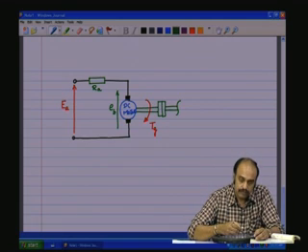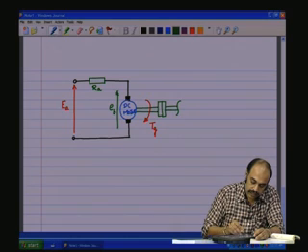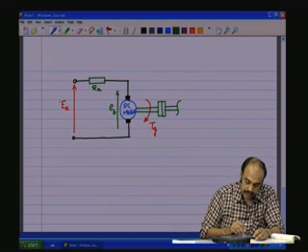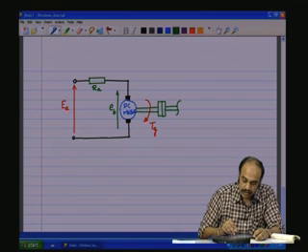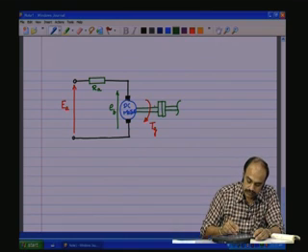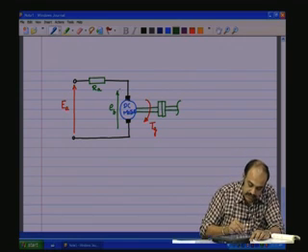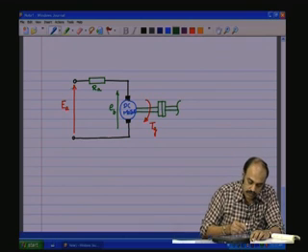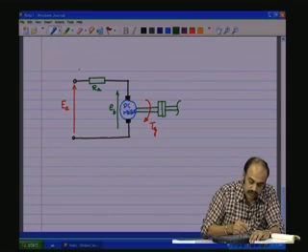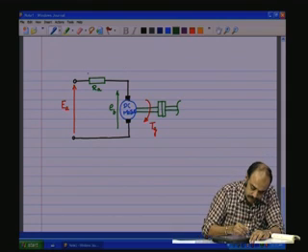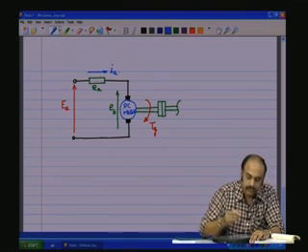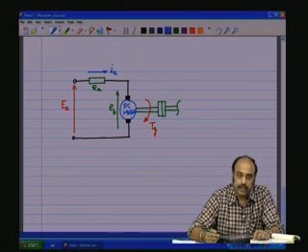and this EMF is called the back EMF because the voltage was applied to make the torque rotate, and this rotating shaft produces a back EMF, and therefore, an EMF which is applied back onto the electrical side. It is the difference in this voltage which is going to get applied across the winding resistance and cause the current to flow through this. So, that will cause a current IA, the armature current IA, to flow through the armature.